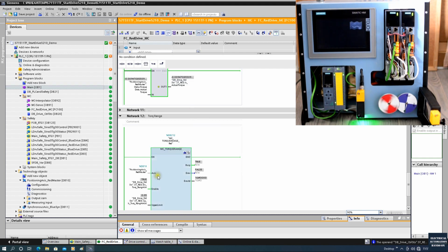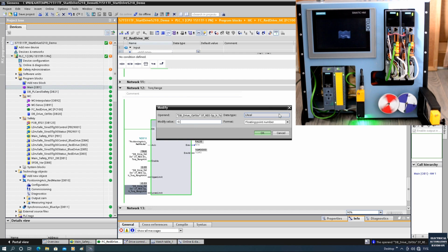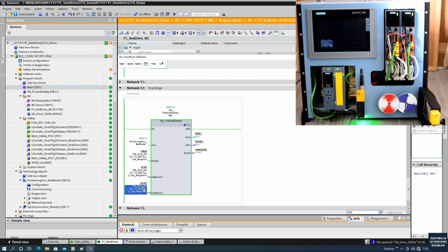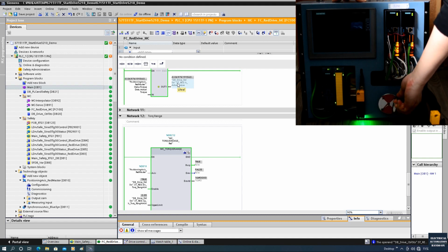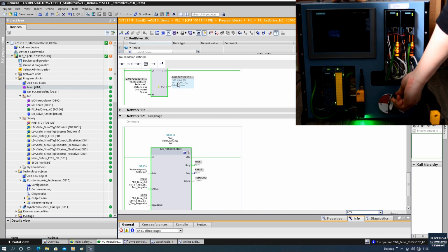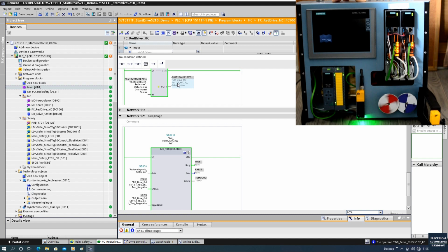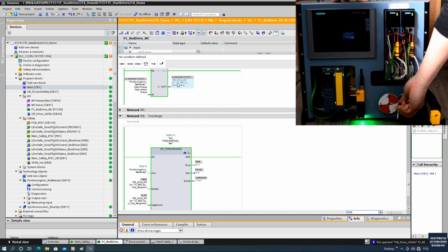And now I enable this torque range, and if I change this value on the fly, so now I change to negative 0.07. And I should feel a stronger torque from the motor, negative 0.07. Okay? And let's see, this negative 0.07 should reach there. Now, apply. I can feel it is slightly harder. But now if I jam the motor, it should show negative 0.07. Release. Okay, runs normally. Apply. Release. I can feel this motor is much stronger. Apply. Release.